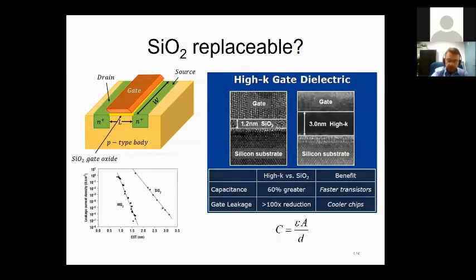Okay, now you have built your oxide, your MOSFET, and you're still trying to shrink down the sizes. While you're shrinking down the sizes, this oxide thickness also will be brought down to a thinner value, like 1.2. But as you're doing that, it's becoming too thin, and the electrons can really punch through that thickness. So you have to change that silicon dioxide. You're not satisfied with silicon dioxide anymore. You change it to what we call high-K dielectrics, to put a little barrier for the electrons.